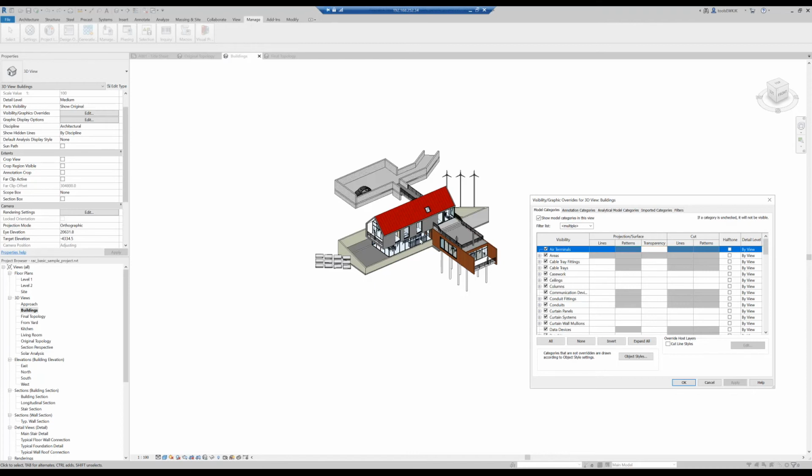What is significant to this simulation? Now, obviously, walls are significant, roofs are significant, this building base is significant, windows are significant. What isn't significant? 2D models of people, pipes, taps, fittings, fixtures, furniture. These are not significant to an external building aerodynamics problem. And although SimScale is incredibly robust to geometry, there's no point making our lives hard for ourselves. So we might as well get rid of them when we export. So we can work our way through.